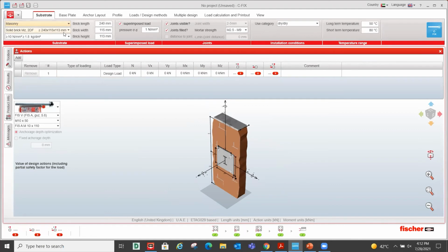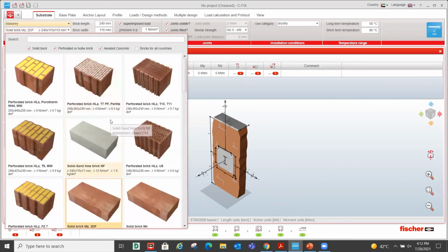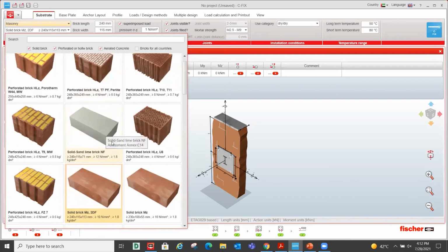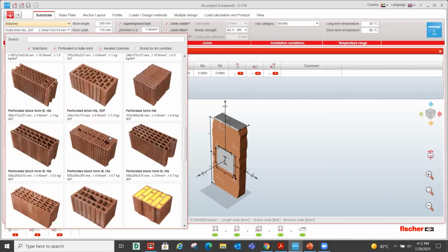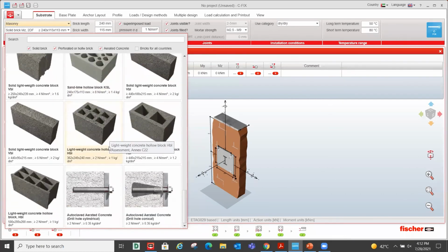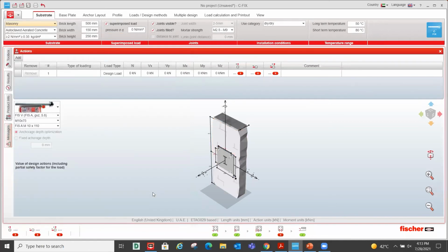We have options in this software, starting with insulation, insulated block. We also have solid block, hollow block, as well as aerated concrete. This is basically known as white block, but it is autoclaved aerated concrete block. Doing a calculation here is a bit challenging. However, our software gives the option to choose this AAC block and make the calculation same as concrete designing.